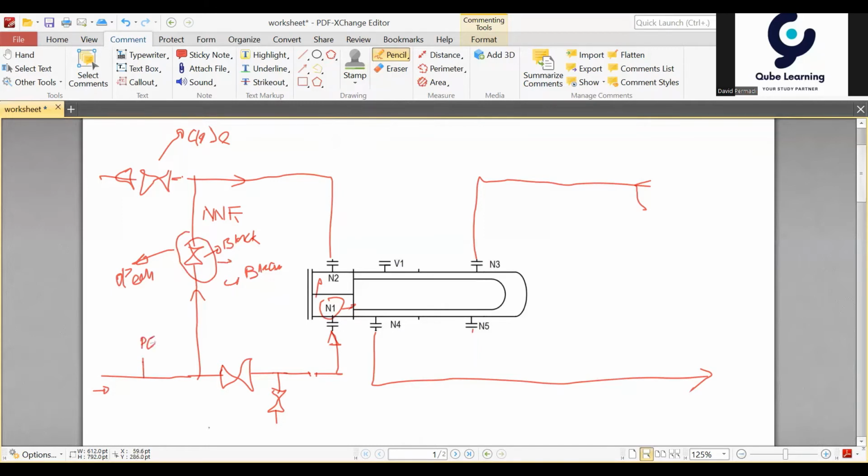Yes, as you know, the cooling water is quite dirty compared to the process fluid, so we have to install two PGs here to ensure we have the value of the delta P, or pressure drop, inside the tube side of the exchanger. And then we also have to put a temperature gauge at the outlet of the cooling water exchanger,